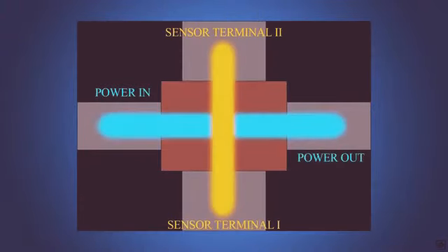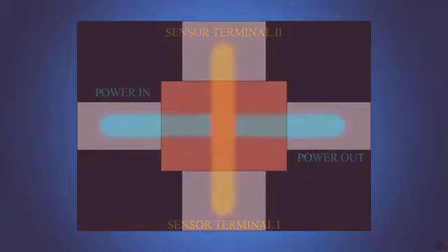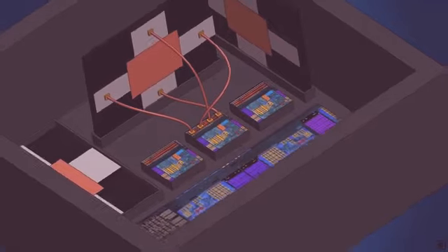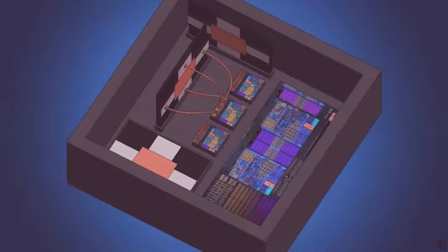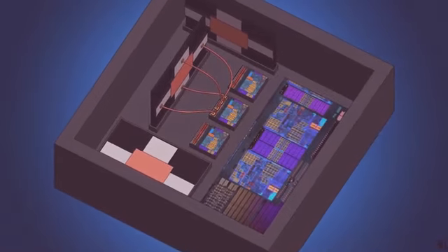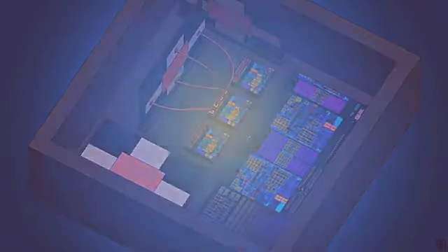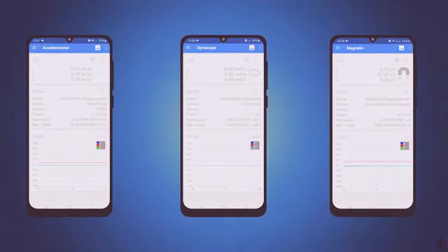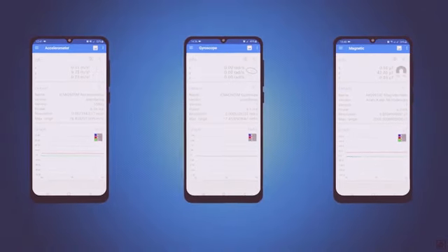Its microstructure looks like this. For using this sensor in three directions, we have to use three different sensors, all perpendicular to each other. Now with the value of the magnetometer, we detect the direction of the north. Combining the magnetometer data with the gravity and true acceleration vectors, you'll get the full orientation information.